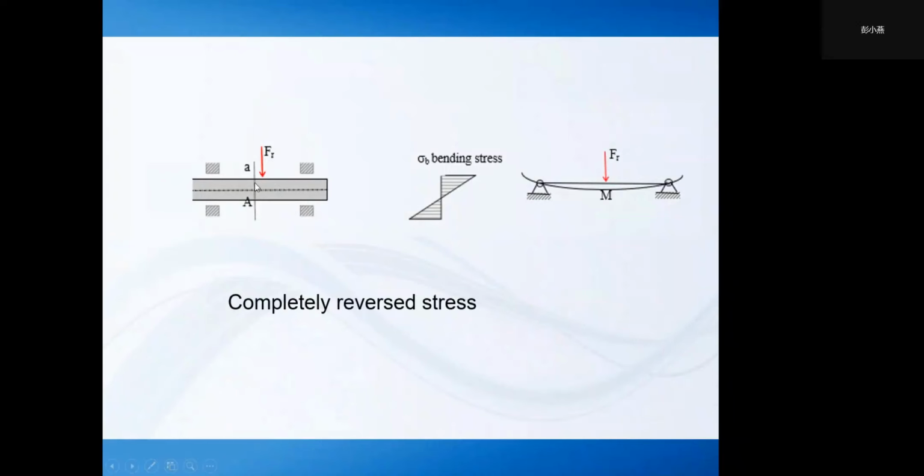In this position, the point at the bottom of the shaft experiences a tensile stress, while points at the top of the shaft have the same magnitude compression stress.